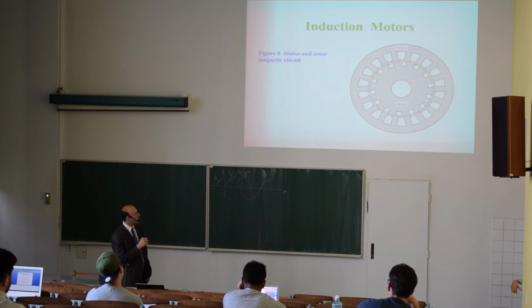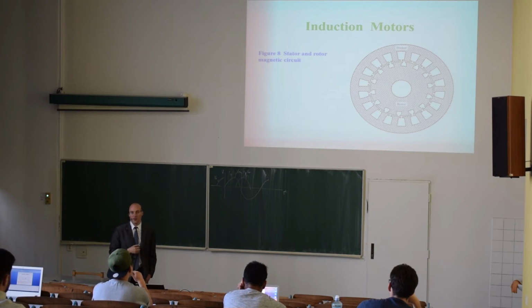If I break the rotor and I take the voltage from the rotor to some load, it would be a transformer working from this winding into the rotor winding, and the amount of voltage that is being induced depends on the rate of change of magnetic flux. So for a transformer, we have used the factor that we called P, the transfer coefficient, saying the voltage in this one winding is being induced in the other winding.